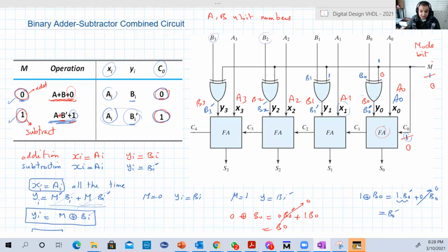design example, the first example that we took in combinational circuits, okay, we built the truth table, and from the truth table we built a Karnaugh map. Then from the Karnaugh map we minimize the functions, the outputs, and we build the circuit, and the same for the full adder and the same for the half adder. Okay, but where is the truth table here?